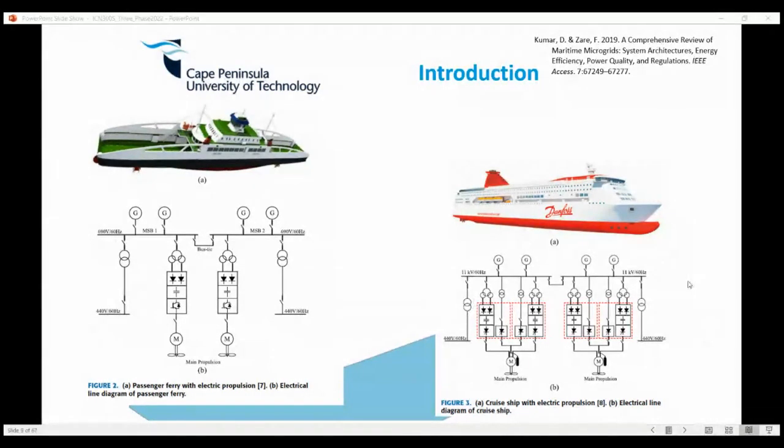In my limited experience, it's just the big ships that don't need to maneuver and don't have to worry about crew and passenger comfort. The directly coupled slow-speed diesel is still the most efficient way of getting the ship to move. Then the cruise ships and things that have to maneuver in tight situations and have to consider vibrations and things like that, they use a bunch of small engines. I appreciate that. I didn't even know that. That makes sense.